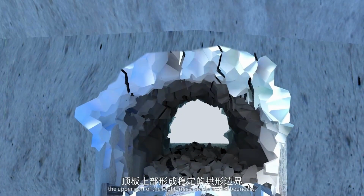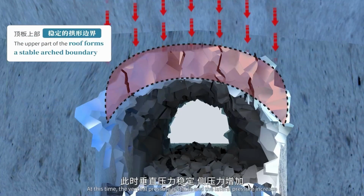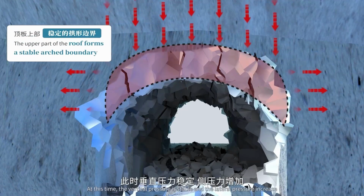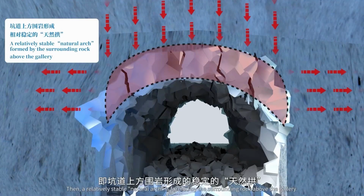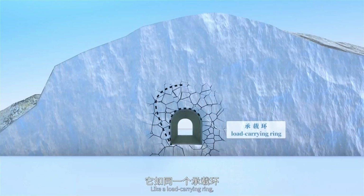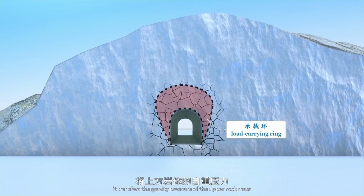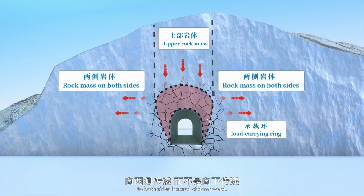When most of the fallen rocks are separated from the parent rock, the upper part of the roof forms a stable arched boundary. At this time, the vertical pressure is stable and the lateral pressure increases. Then, a relatively stable natural arch is formed by the surrounding rock above the gallery. Like a load-carrying ring, it transfers the gravity pressure of the upper rock mass to both sides instead of downward.